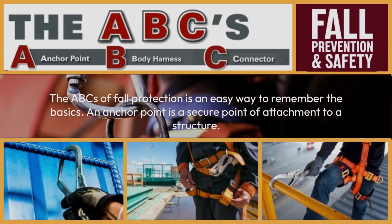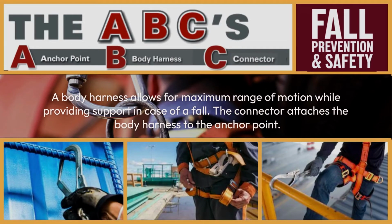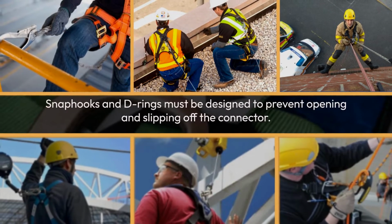The ABCs of fall protection is an easy way to remember the basics. An anchor point is a secure point of attachment to a structure. A body harness allows for maximum range of motion while providing support in case of a fall. The connector attaches the body harness to the anchor point.